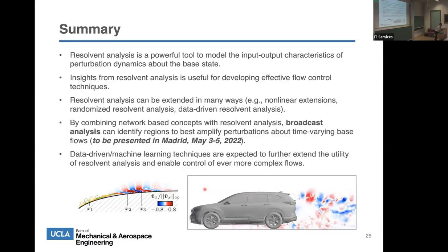If you want to spatially localize the input, you can do that using the C and the B matrices, right? So would you get the same thing if you localize like that? That's actually a good question. You could artificially force it to say, I want my input only in this region or on this surface, but that doesn't narrow down to a single point yet, right? You could choose it. But that doesn't mean you're solving some optimization problem to give it a little bit of freedom. You're actually narrowing it down to that point and seeing only the response. So you're not solving for the location at that point. You could, yeah. But that would be a parametric study that you'd have to do, right?